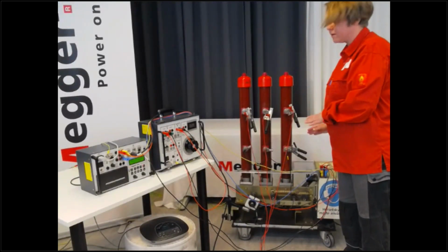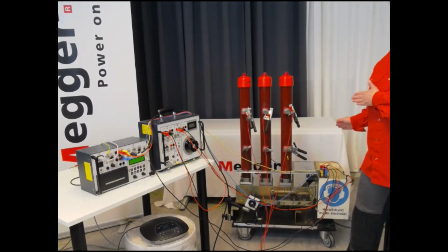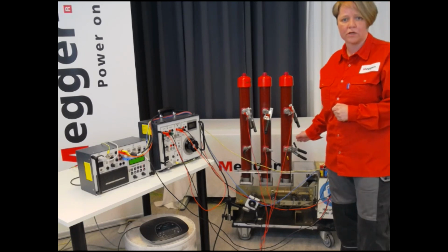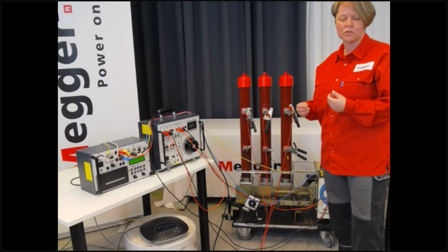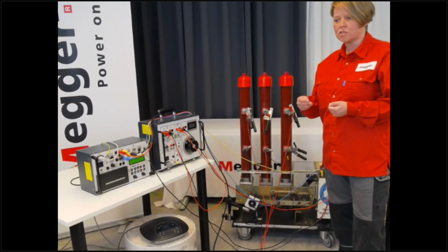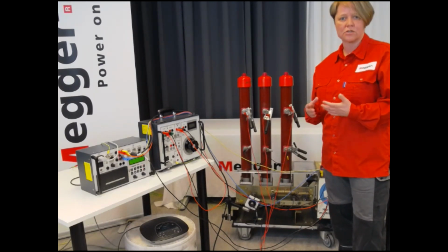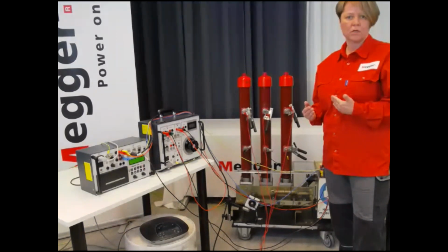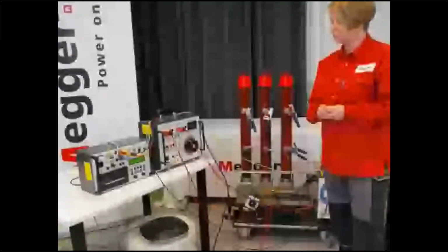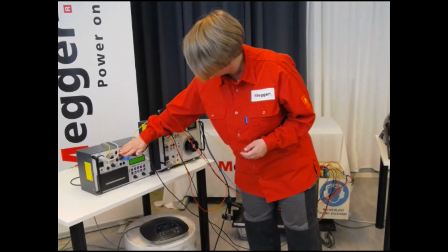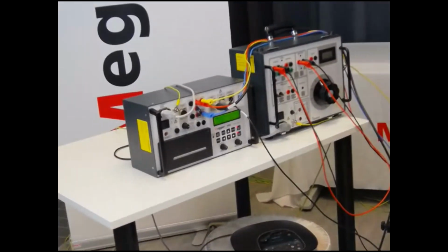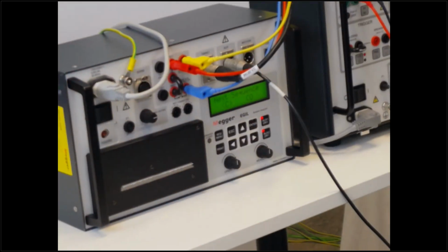I can also mention that now when I connected the controls, it's important to go via these auxiliary contacts, because as I said, they are like a safety. And also there are things like the spring charging contact in the circuit, so the circuit breaker is prepared to do the operation. So you don't send pulses to the coils when it's not prepared. So I have the controls via the auxiliary contacts, the timing, and the auxiliary contact timing. Now I have one thing left, and that's the motion. The motion is prepared here.